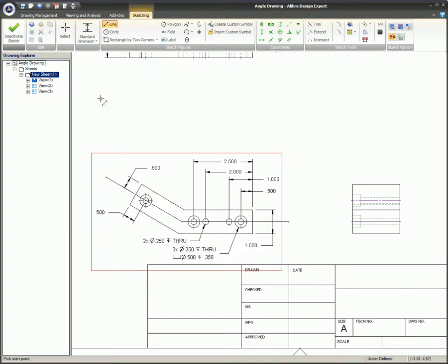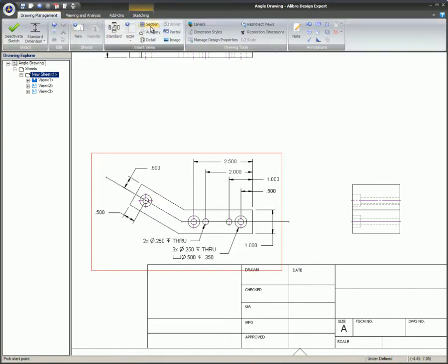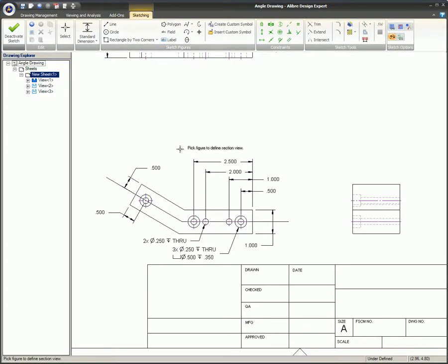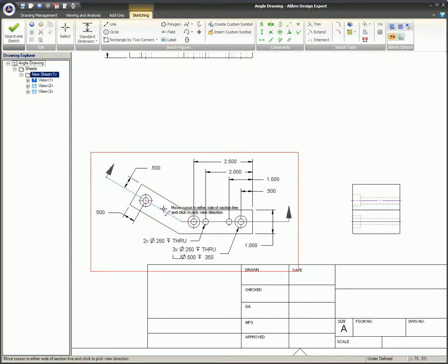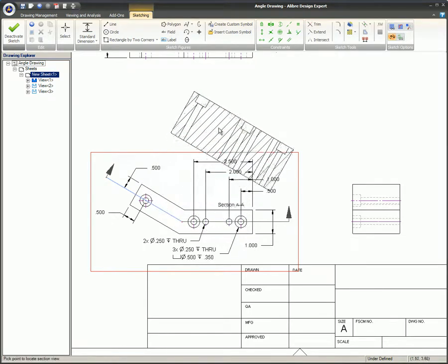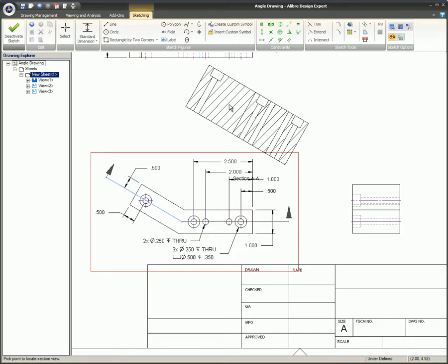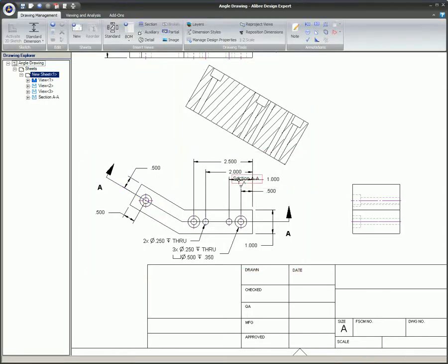After your section line is sketched, if it is created with more than one line segment, the segment of the line that you choose will provide the perpendicular angle for the section view. This section line is composed of two lines, the horizontal line and the angled line. The mouse is currently hovering over the angled line and is denoted by that line being red. If this angled line is selected, the section view will be perpendicular to this line. This newly created section line can be moved to a new location, but by default it will be perpendicularly aligned.